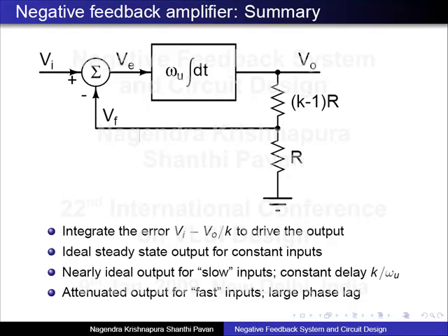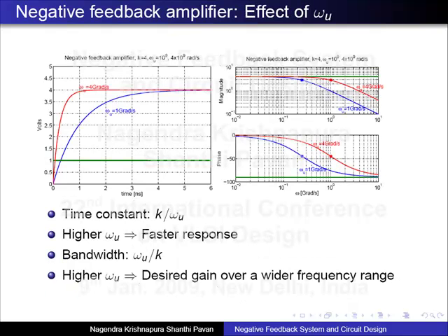No, it is a low pass filter. No, omega u is a constant. In fact, if that is a function of time, it becomes some kind of time varying system, and we can't even represent such a thing with a Laplace transform, right? No, omega u is a parameter of the integrator, right? It has nothing to do with the voltages that you apply to the integrator. Okay, omega u is a parameter of the integrator.